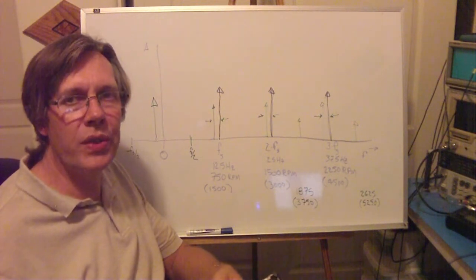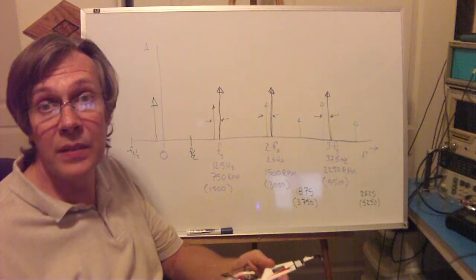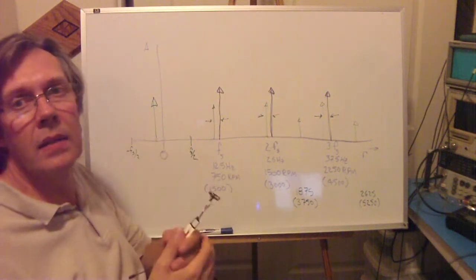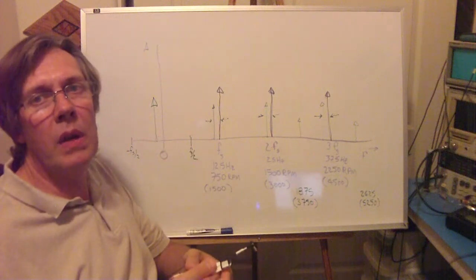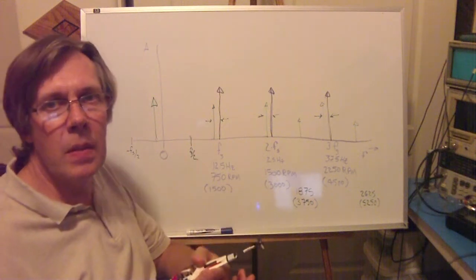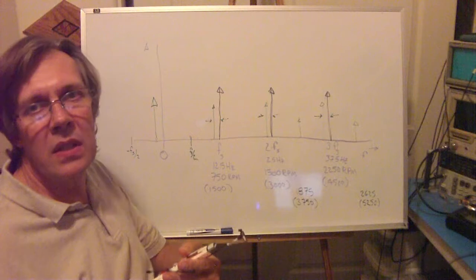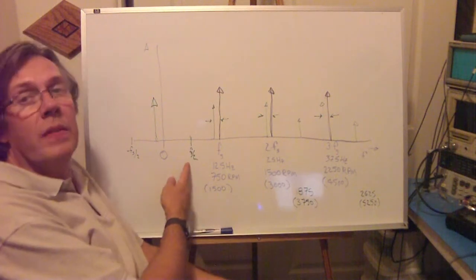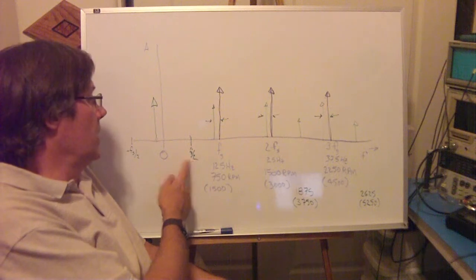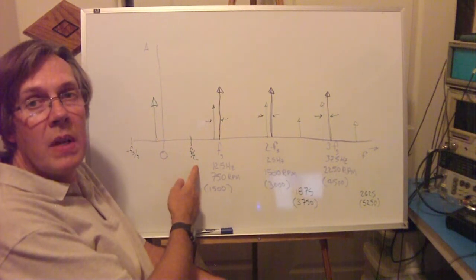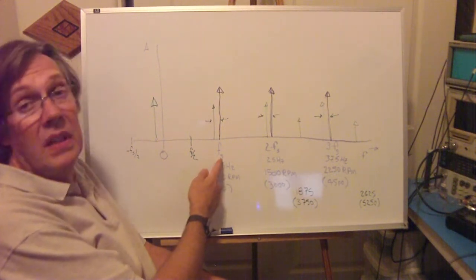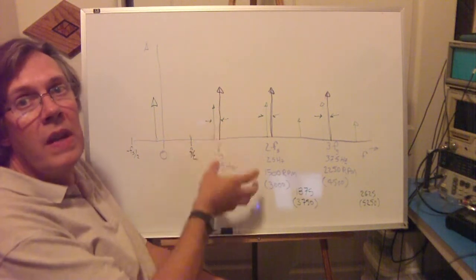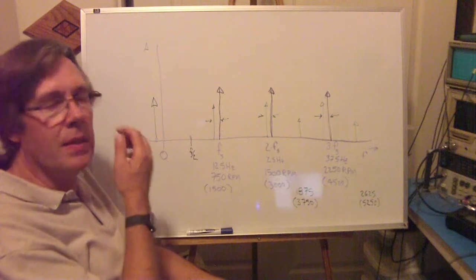Nyquist, one of the guys that originally figured this out in the context of telegraph systems, came up with the usual criterion, the Nyquist criterion, that we hear about, which is for a real valued system, whatever the highest frequency in a system is, you have to sample it at twice that. And that's basically what we figured out right here, that if you want to support frequencies up to f sub s over 2, you have to sample it at least f sub s in order to make that non-ambiguous, so that you don't have energy folding back in as an alias.